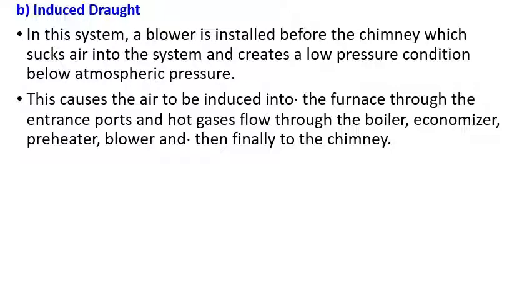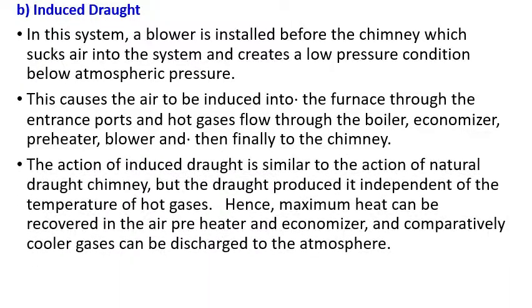So this causes air to be induced into the furnace through the entrance port and hot gases flow through the boiler and economizer. The action of induced draft is similar to the action of a natural draught chimney, but the draught is independent of the temperature of hot gases. In the natural draught we have seen, only when the temperature is high will it operate smoothly. But here it is not so. At any temperature, I can create or dump the draught, drawing the flue gas into the atmosphere.